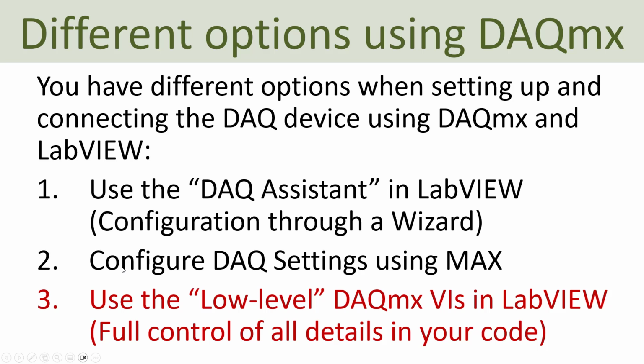Then I showed an alternative solution where I configured the DAQ settings using the Measurement and Automation Explorer, and then used that configuration in my LabVIEW program. And now finally I will use the so-called low-level DAQmx VIs in LabVIEW, where by using those low-level VIs, you will have more control or full control of all the details in your application.